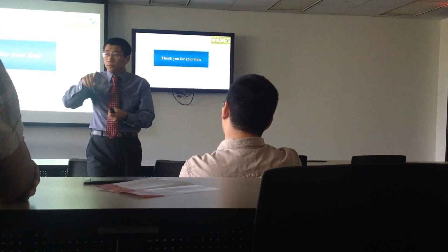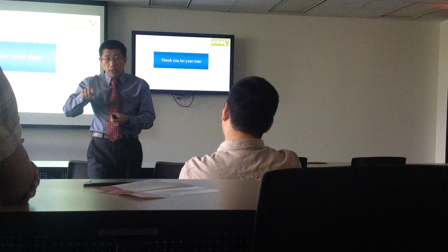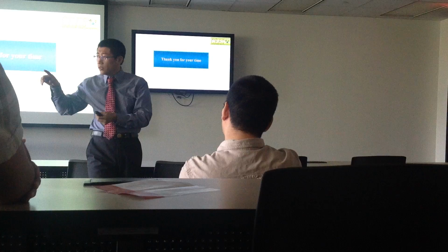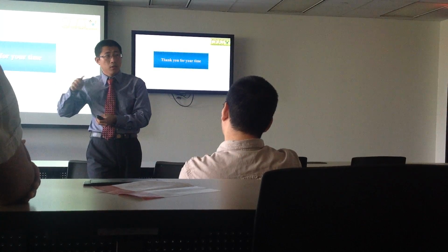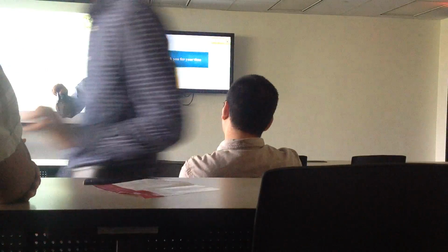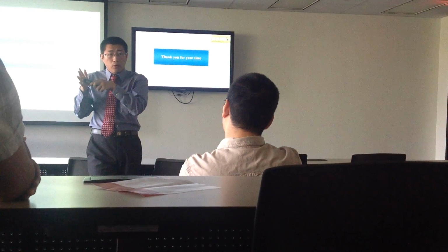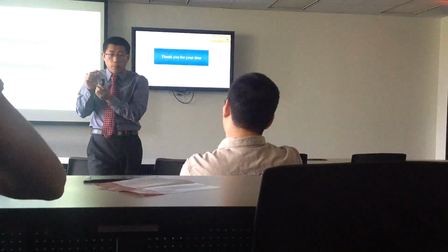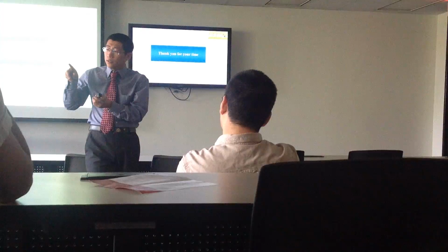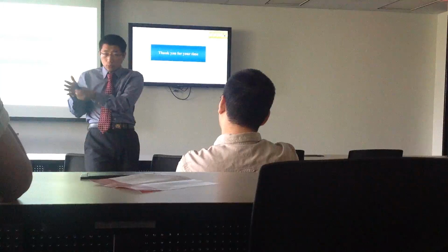For Y plus less than 30, we achieved Y plus less than or equal to 29. And for Y plus less than 150, we achieved a value around 148 or 149. It's very close to this value, and it can change a little bit by 1 or 2, but it should not be close to 130 or to 30. It should be close to this value.